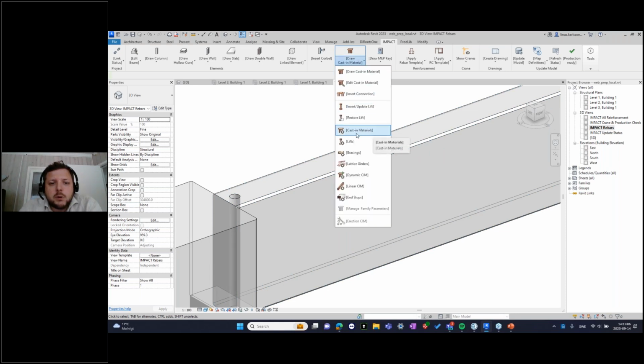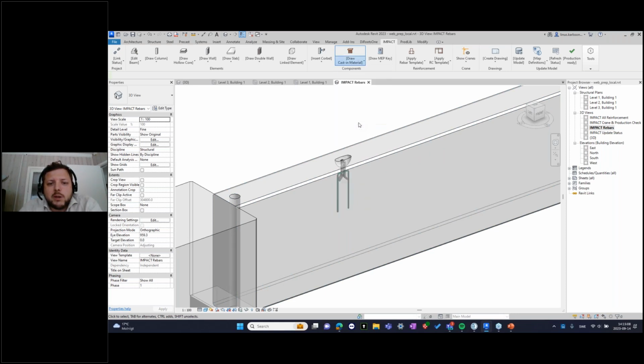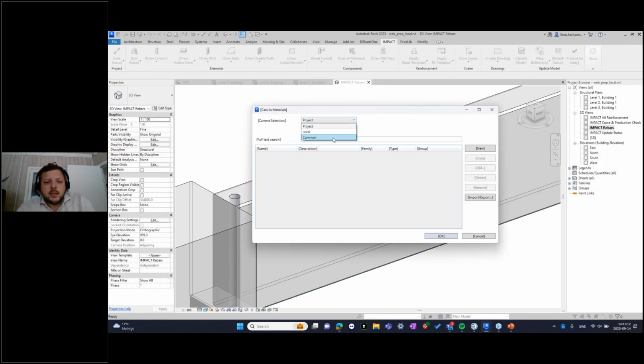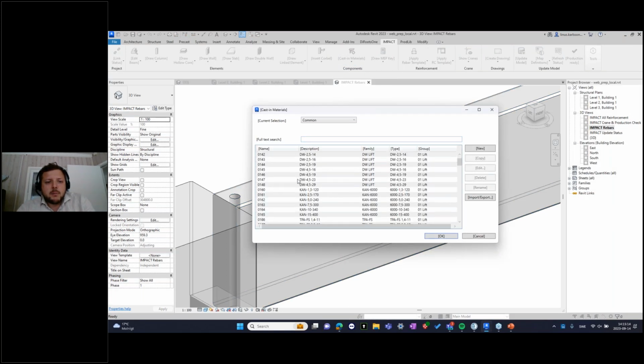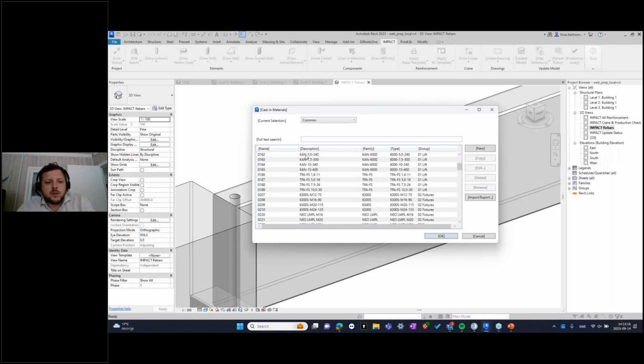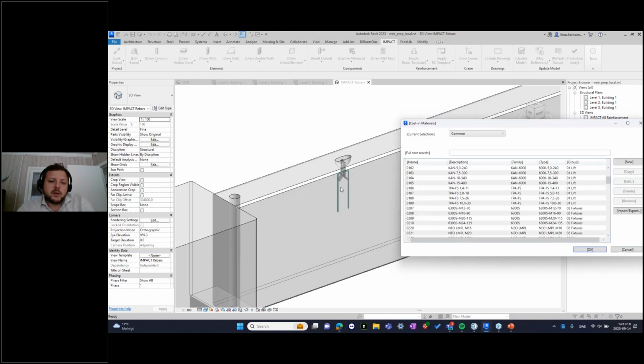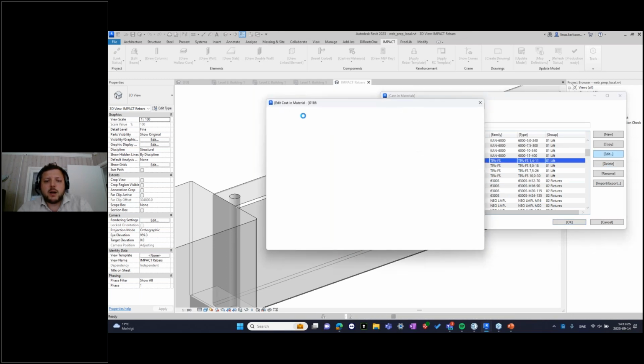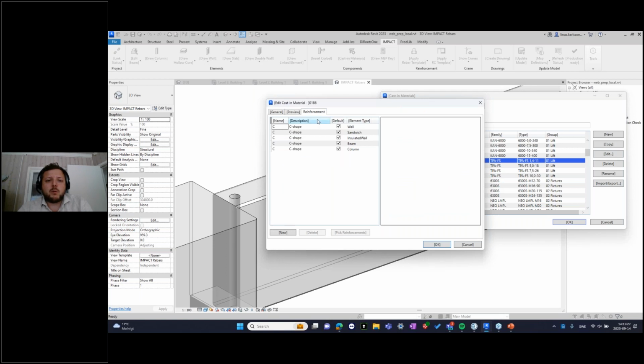So it's pretty easy. You would just go into the definitions. Oh, I can show a little bit here. So you go to the definitions, or basically you draw this in the model, and then you go to the definition and edit, and then you have a tab up here with reinforcements. So you create one or more options for each element type.